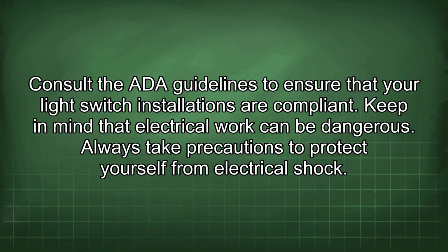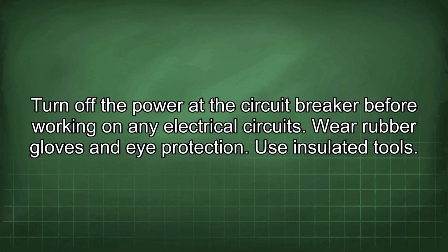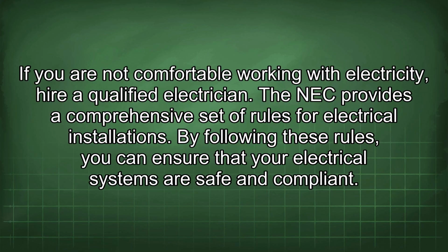Keep in mind that electrical work can be dangerous. Always take precautions to protect yourself from electrical shock. Turn off the power at the circuit breaker before working on any electrical circuits. Wear rubber gloves and eye protection. Use insulated tools. If you are not comfortable working with electricity, hire a qualified electrician.